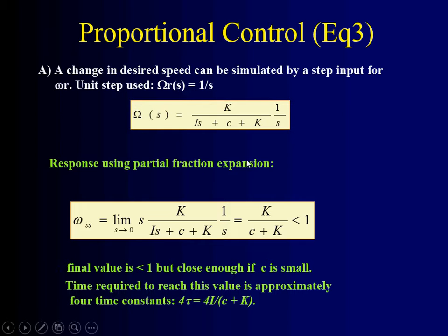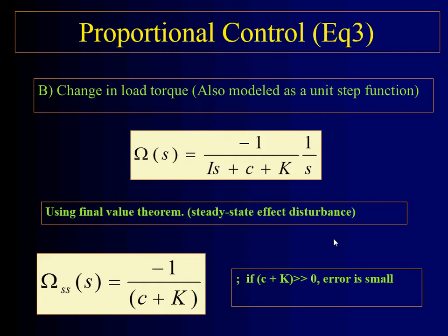As the output approaches the final value without oscillations, the time to reach this value is inversely proportional to the control gain. Meaning the more control, the faster it's going to get there. The output deviation due to the disturbance at the steady state is inversely proportional to the gain. And the error will always be present even in the absence of damping.